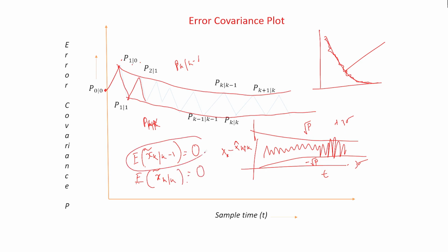Okay. So, this is your predicted error, predicted thing, there is no bias, and this is the estimated state. So, the Kalman filter is an unbiased estimator. This is a very important concept. If instead of 0, you see some constant value C, that means your measurement is biased and your Kalman filter won't work. If this is your truth, you will get an estimate like this or an estimate like this. So, some constant bias will be there. Okay. So, your estimate has to be bias free.